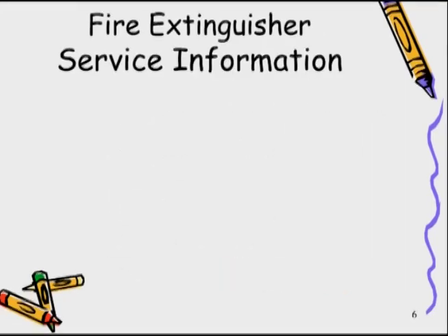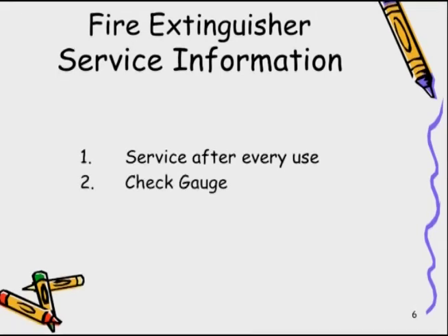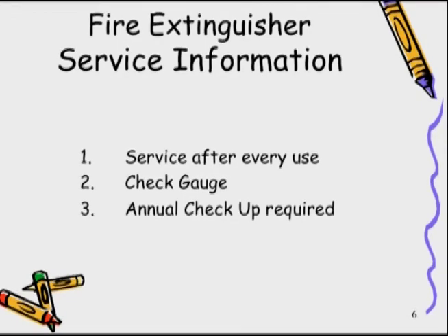Let's talk about servicing the fire extinguisher. The fire extinguisher will need to be serviced after each use. You should frequently check the gauge to ensure your fire extinguisher is properly charged, and an annual inspection and recharging is required for each fire extinguisher.